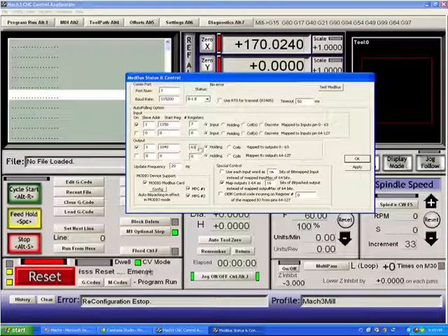So that's outputs to a ModBus and inputs from a ModBus for pin 0 to 63 of port 0. In addition to that, for PLCs like the DL5 and DL6, you can send in analog values. And we call these pins 64 to 127. Anything coming in on this second line from the ModBus gets sent to an array in memory, which are reflected by pins 64 to 127. We don't use those in the pins and port configuration. We only use these in macros.